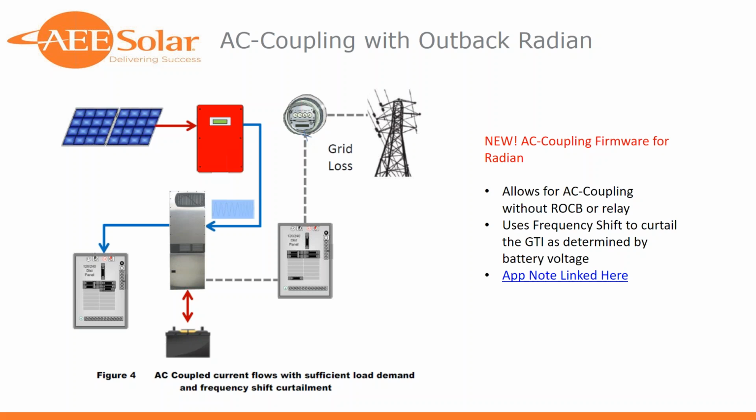If you've ever worked on systems at the end of a long feeder line off of a transformer, you know that sometimes the quote-unquote grid in a given area is not a nice, tidy 120/240 at 60 hertz. Sometimes the voltage is high or low. Sometimes the frequency can be really low. In short, the grid-tied inverter needs to see a qualified grid.